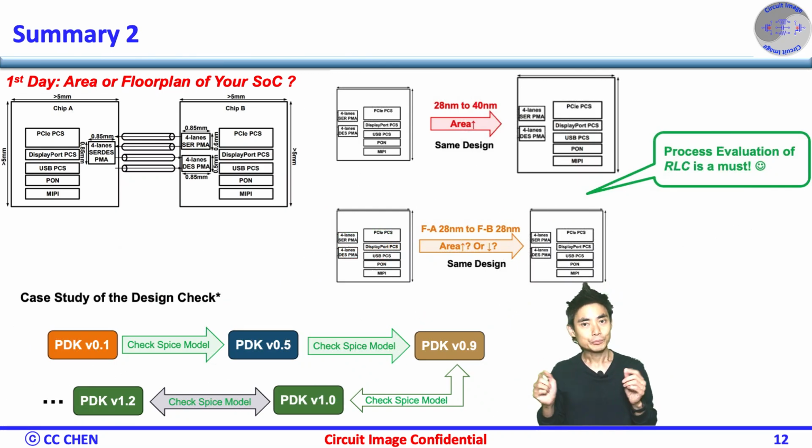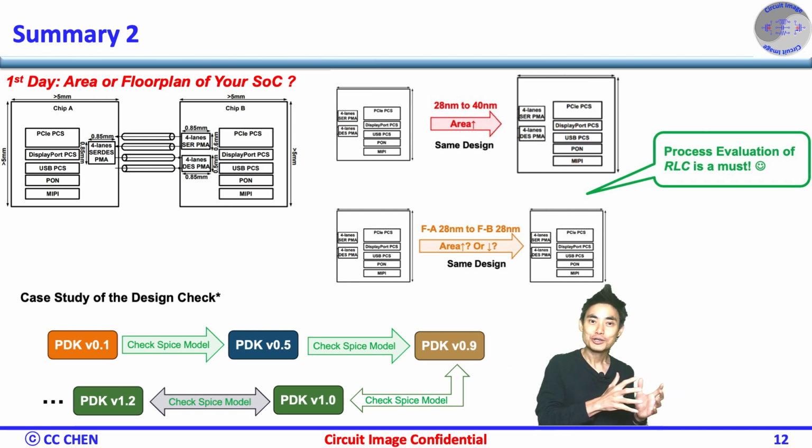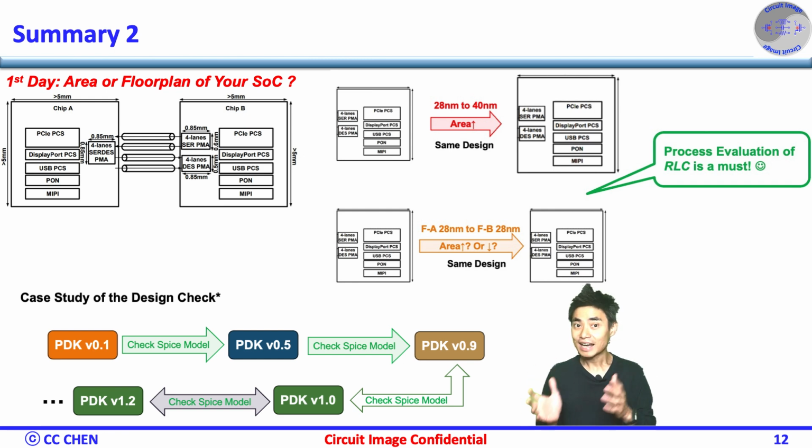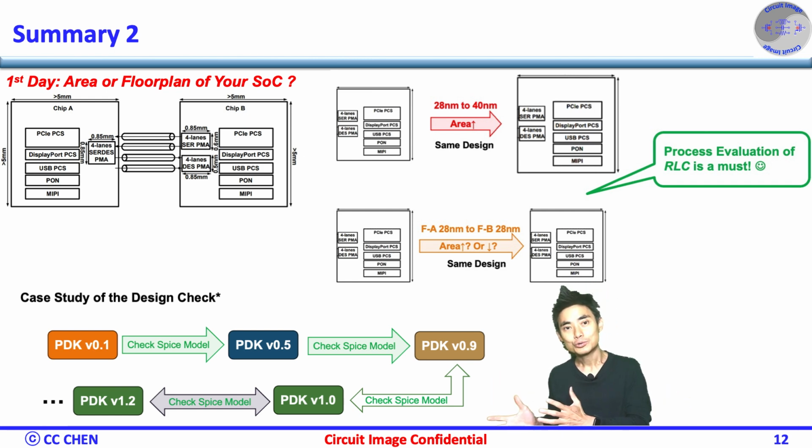correct, if you plan to port the existing design from one process to another process node, you must understand what the passive characteristics are before deciding the next process node. For example, you must make sure about the smaller resistance and capacitance in the next process node, which you made the right decision. Otherwise, with exactly the same design parameters, you must increase the area and redo the floor plan, which could be a big issue and usually occurs from an advanced node to an older process node.